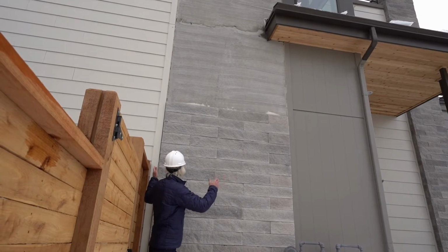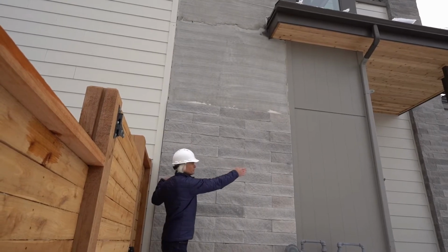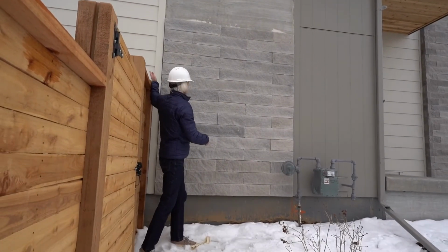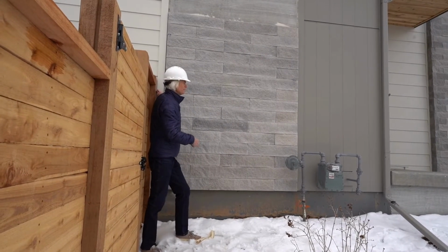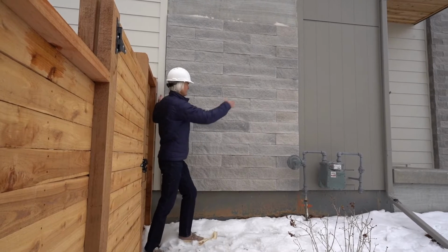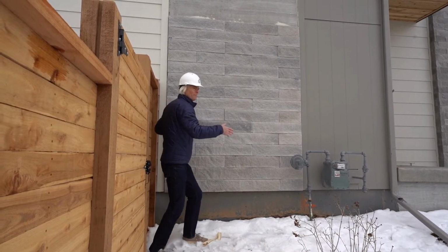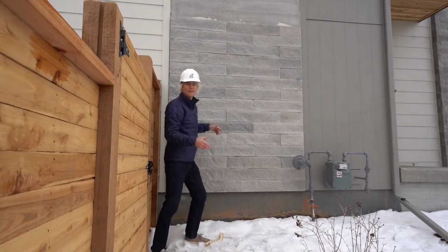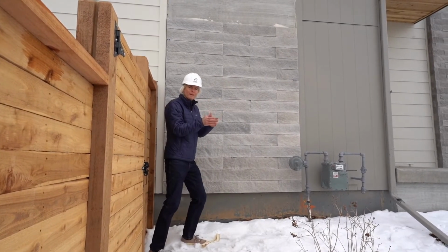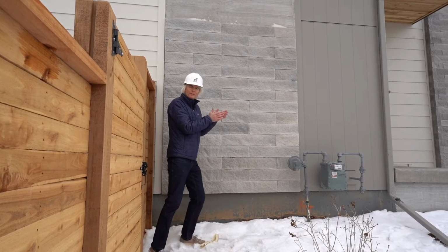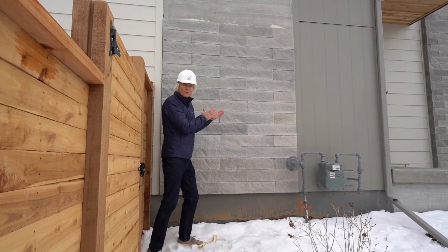But also on the left and right sides, we're going from a cement panel siding to a lap siding with basically a 1x4 strip that's edging both of those. So we've got this thin, looks like about a 6-foot wide patch that goes 25 feet into the air of stone on a scratch coat with expanded metal lath and two layers of grade D paper over a wood sheathing.